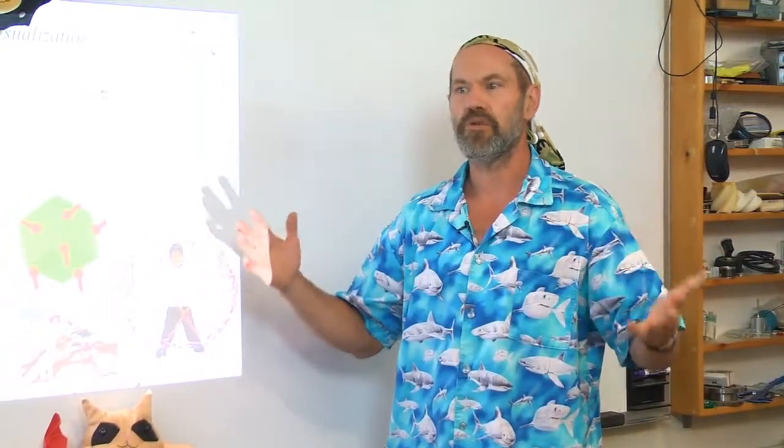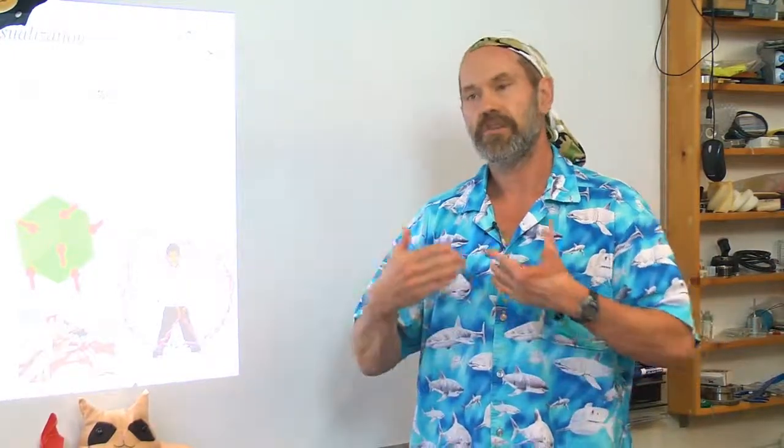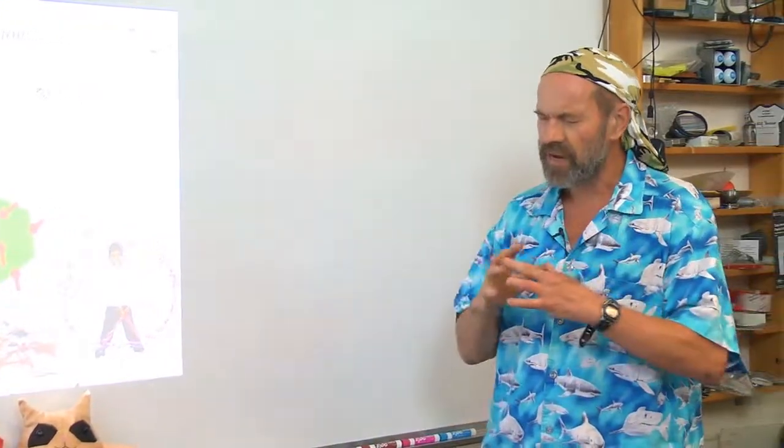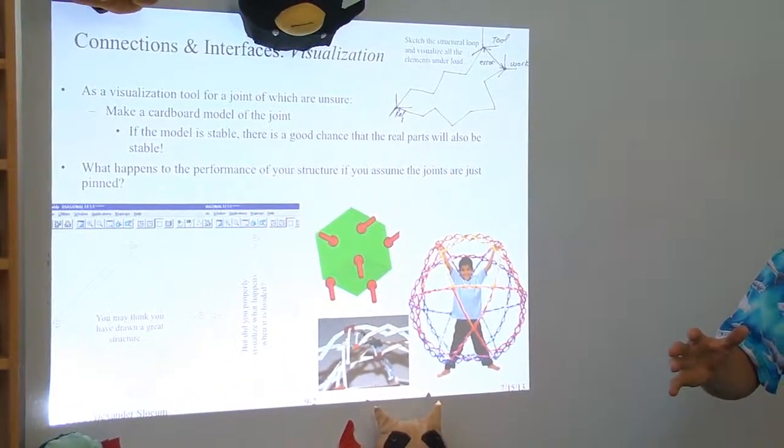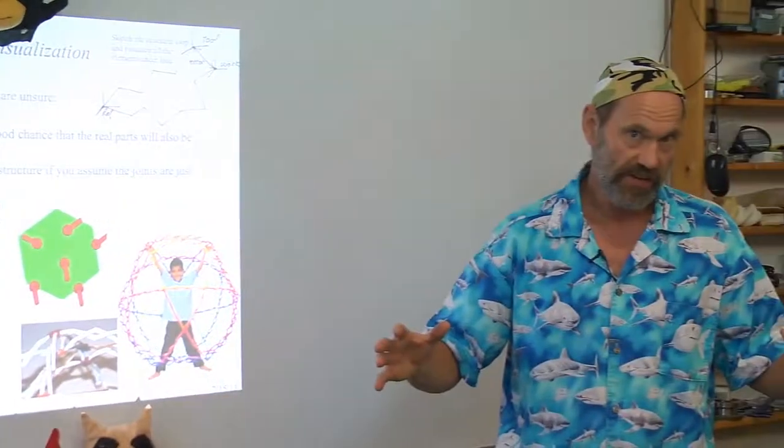The first thing you want to do is visualize your joint. What must it do? This is part of establishing the functional requirements, the specific functions it must do in terms of strength, stiffness, repeatability. Play the movie in your mind of how things move. You may create a beautiful solid model or picture of your device, and if it doesn't move, it just sits there. That doesn't do you any good, right? So you will have to either animate it on the screen, or, especially during the early phases of design, learn to play the movie in your head.